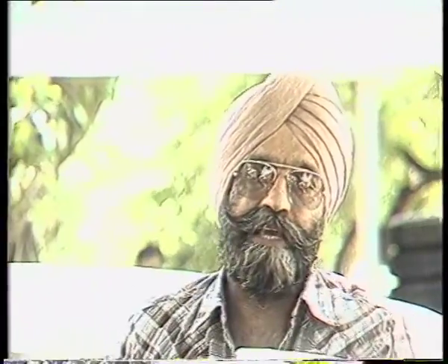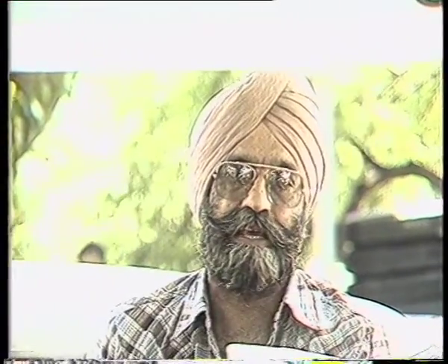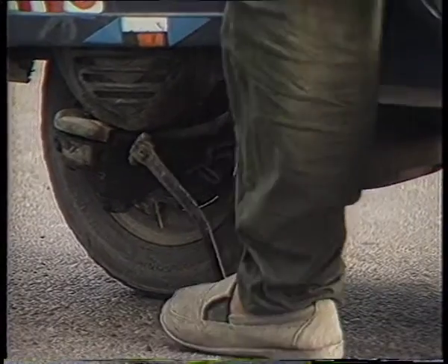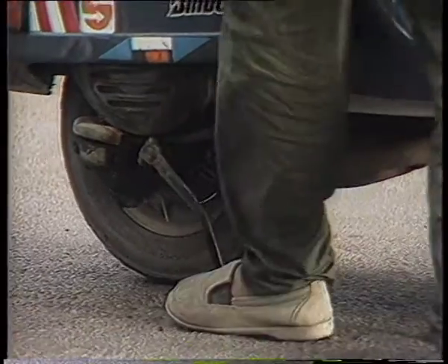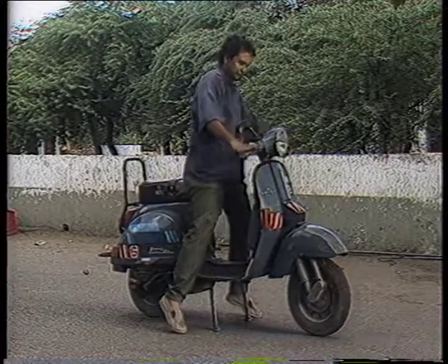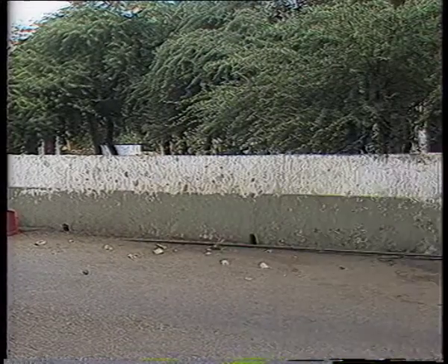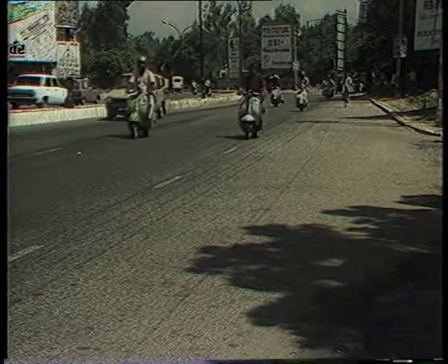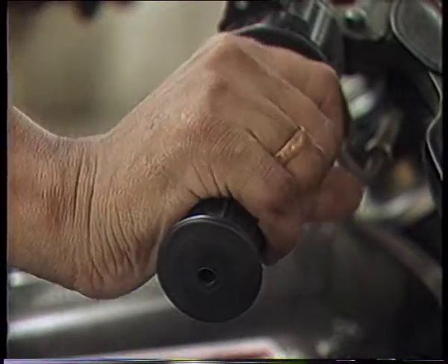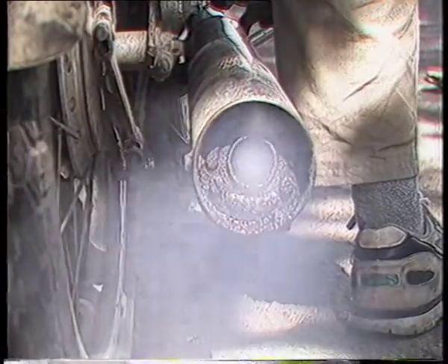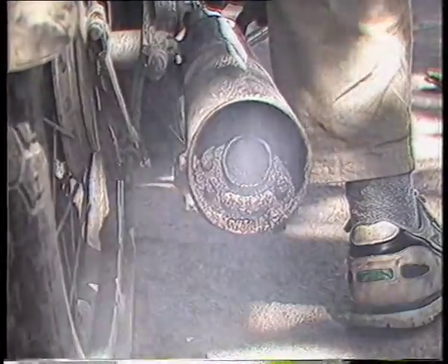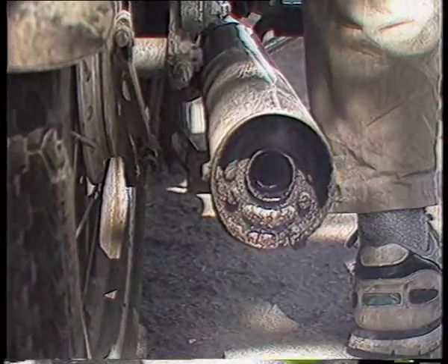You may be wondering why the engine requires rich mixture at the time of starting and at full throttle open operations. This is because initially the engine and carburetor are cold, the airspeed is low, and much of the fuel does not vaporize. Thus, an extra amount of fuel must be delivered by the carburetor so that enough will vaporize for starting. Likewise, sudden opening of the throttle for acceleration allows a sudden rush-in of air. Extra fuel must enter at the same time to provide the proper proportions of air and fuel to the engine.